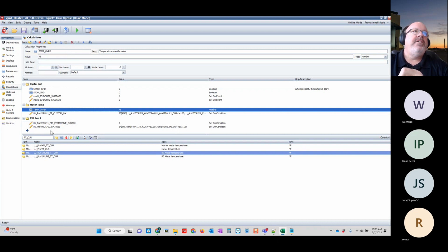That 80 then becomes a tag, and you put that on a display, and then you can change it via the web interface. Ultimately, that's what I try to do for everything, because we know a lot of things are changing, and you don't want to have to write the application back down to it. So it's easier just to create that second tag, like we did for the temperature override, and then put it on display so somebody can change it coming into the displays.